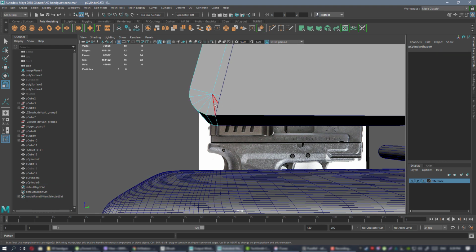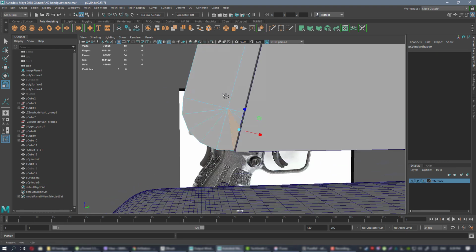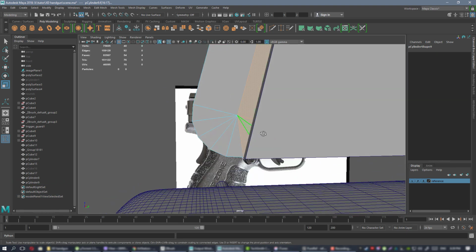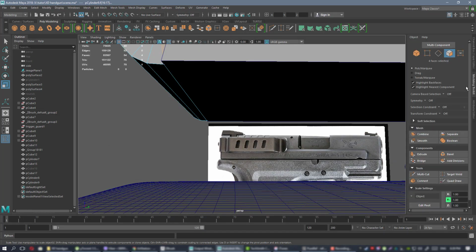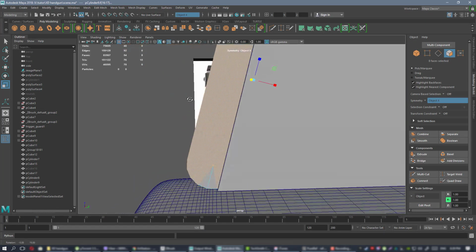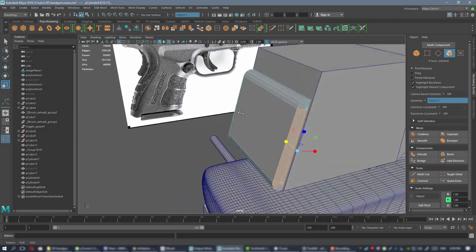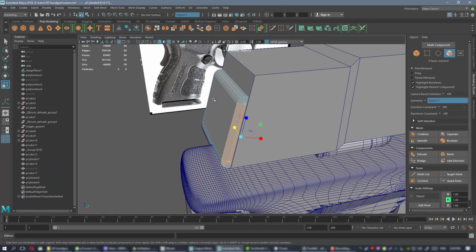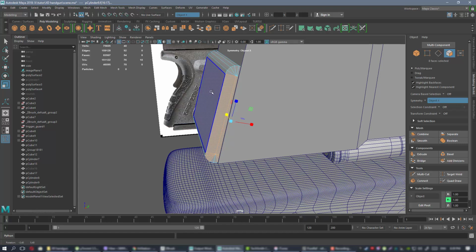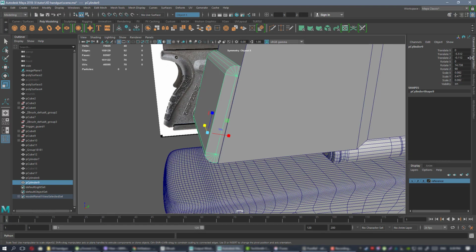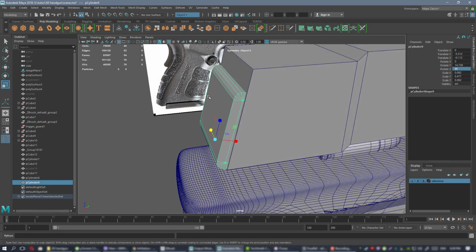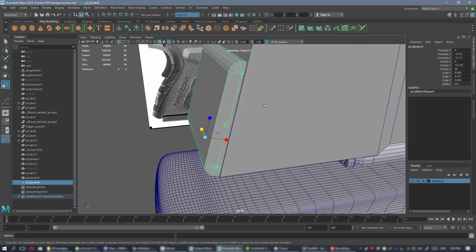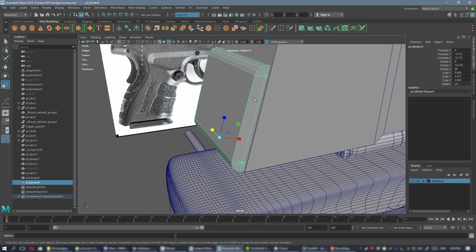And so what I'm also going to do is delete those faces that I don't need with my symmetry on. Whoops. Okay, as you can see right now, the symmetry affects this object in the wrong way. That's because it is rotated right here 90 degrees, as you can see, and it is applying the symmetry locally on this object.